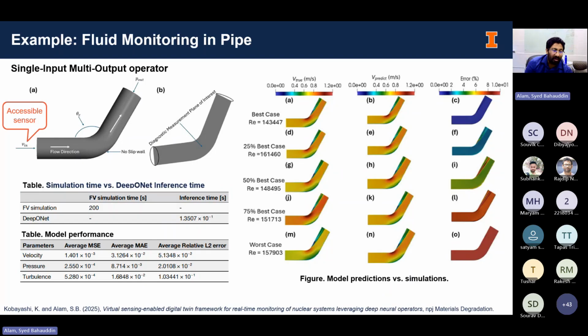But still, there's a catch, because this algorithm worked well as long as the turbulence is lower. That means the lower Reynolds numbers. But the moment Reynolds numbers are too high, things went pretty out of control. What does it mean? This is not actually the silver bullet, right? It works when the turbulence is manageable, but when the turbulence is on the transient side, this model just pretty much failed terribly.